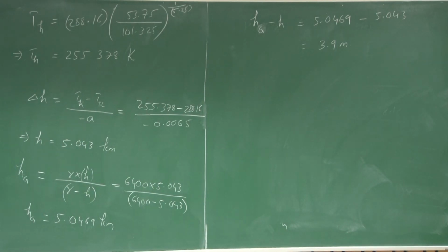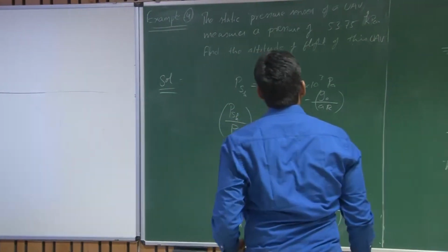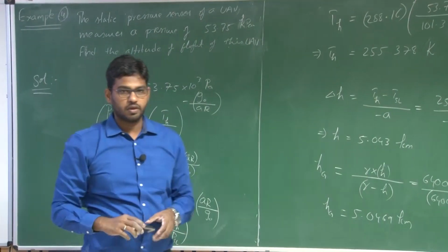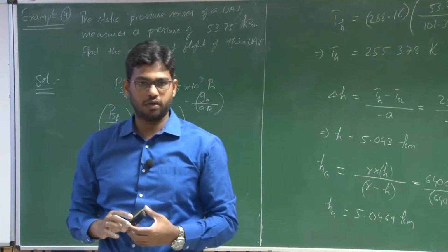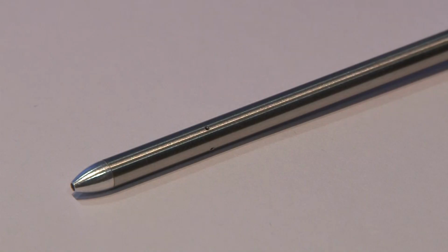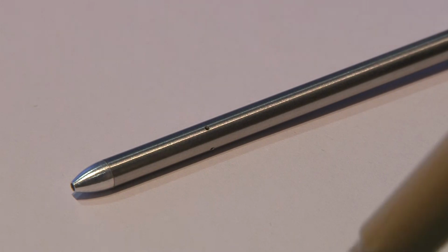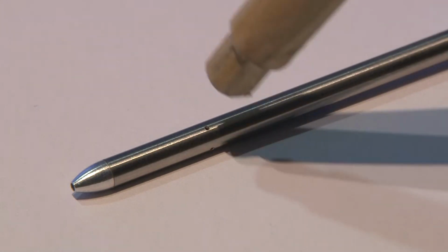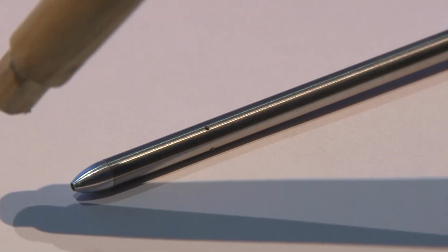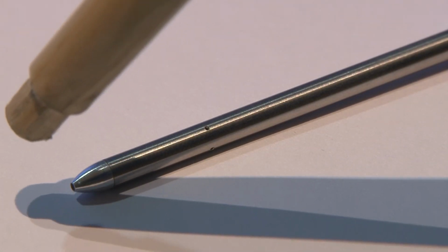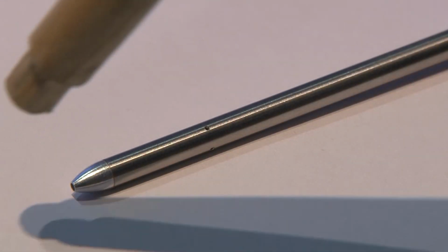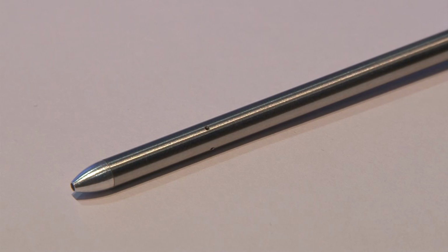Now here we have static pressure, right. So let us look at some of the sensors that we have right now that can measure the total pressure and static pressure. Let us look at this pitot-static tube. See, the holes that you can see on this periphery are meant for static pressure. And you can see one hole which is along the longitudinal axis of this tube, that is meant for total pressure, right.